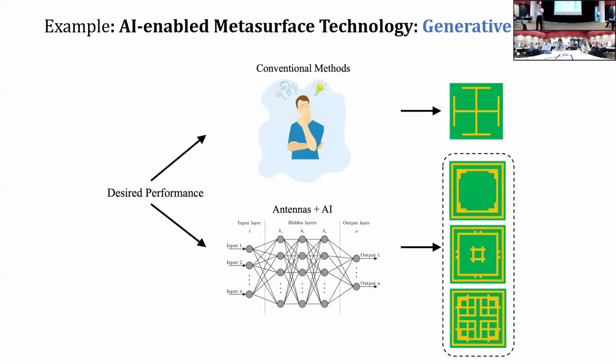For example, I need an inductor, I need a capacitor, and how to link them together. Then I know this is the inductor, because it is just one cell. Coupled to another junction, the cell has the capacitor. So I need the L and I need the C, then I can work out this structure. Usually this structure is very simple and easy to design, but the performance we can achieve is limited. This is the price for this simple design.